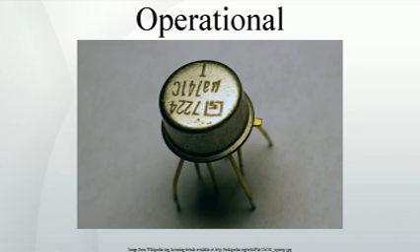The standing current in Q14/Q20 will be a factor exp(100 mV/VT), about 36, smaller than the 1 mA quiescent current in the Class A portion of the op-amp. This small standing current in the output transistors establishes the output stage in Class AB operation and reduces the crossover distortion of this stage.